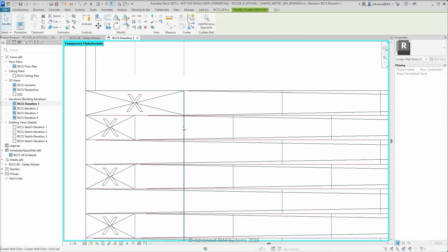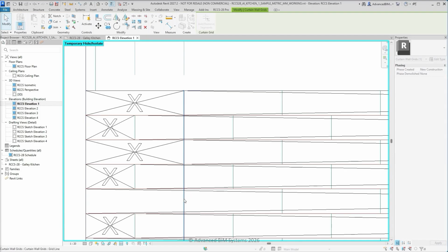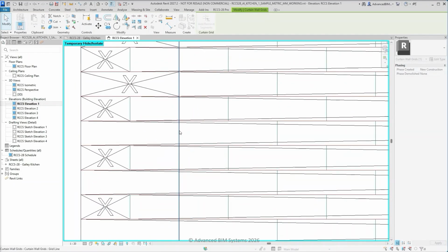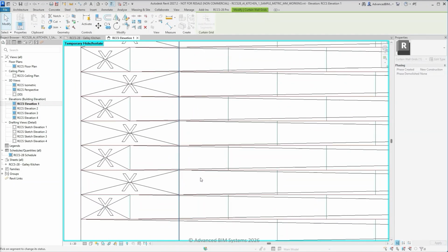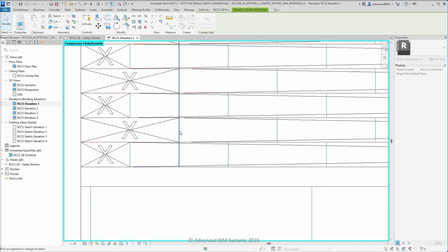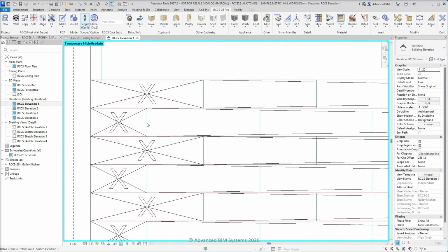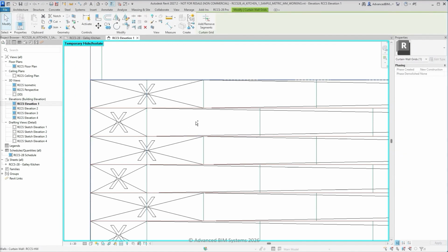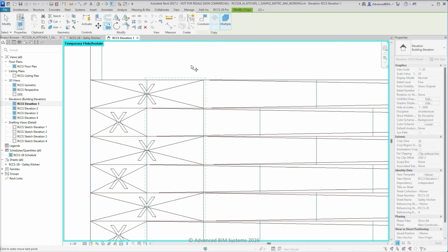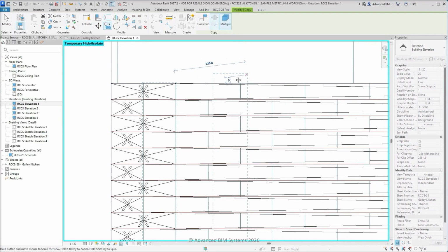Select a vertical grid and activate the Add Remove Segments toggle button to add alternating grid segments to complete the main vertical grids. Select both of the newly created vertical grids and copy them across the center host wall, snapping them to their respective 2D reference sketch lines.